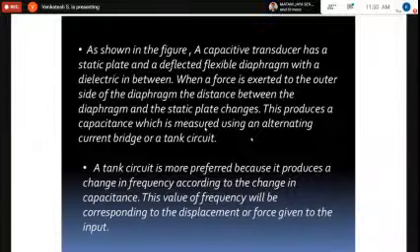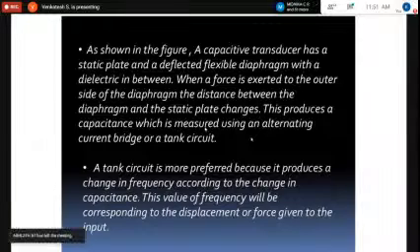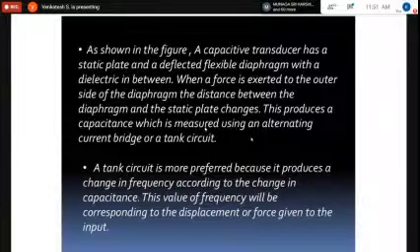Okay. It is the Schering bridge which measures the change in capacitance, like the strain gauge which was placed in the 4 arms of a Wheatstone bridge; quarter bridge, half bridge, full bridge we had seen. Similarly, we can have a reference capacitor and a variable capacitor to form a half bridge, and then an inductor element, so that we get a balance in the bridge.